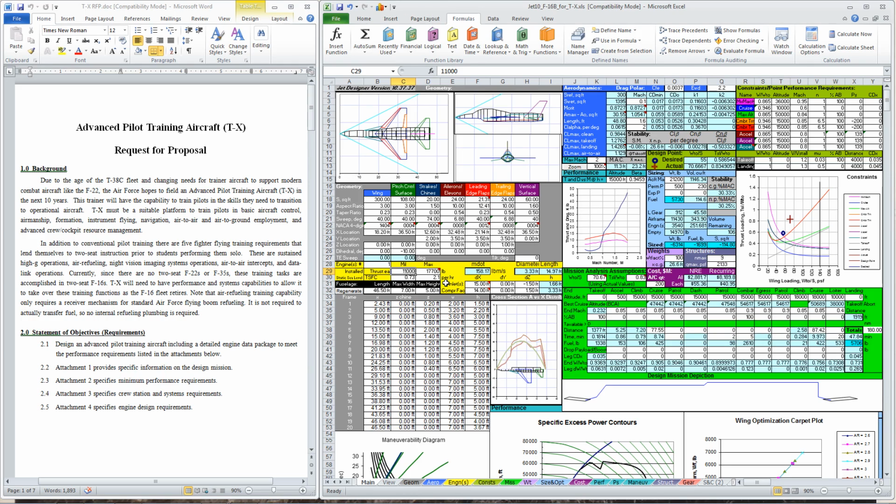Now it looks like we can come down to maybe 6,000 pounds of military thrust. Not quite. Let's see if we can gain some of that back, though. We saved a lot of weight again. We can drop 3,000 pounds. Let's try 17,000. Let's try, oh, that's really close, 17,500. And we've got a pretty good aircraft, except it says we can't do 0.9 Mach at 15,000 feet.